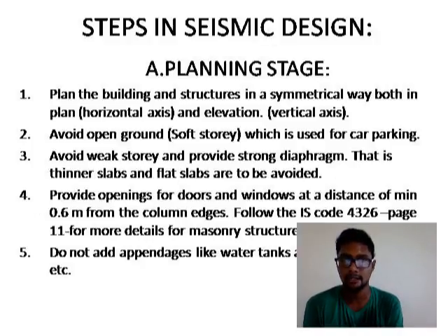The first step is the planning stage. At the planning stage, what are the steps we require for selecting the site? The plan of the structure should be in such a way that it's symmetrical in both horizontal and vertical axis, so that during an earthquake, when the load acts upon the building, the resistance will be equally distributed in the horizontal and vertical direction.